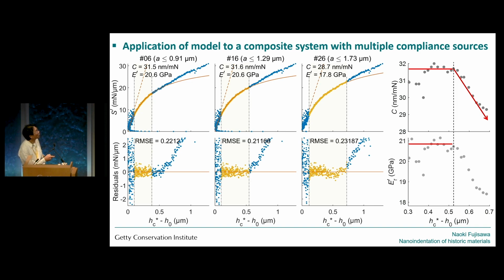But as you go deeper, you begin to see a stabilization of the compliance. Then if you go beyond half a micron, you begin to see a decrease of the compliance, and this eventually goes to a negative value, although we didn't go that far. The same applies to modulus. You see a flat modulus profile up to certain depths, beyond which you begin to feel the effect of the underlying material.